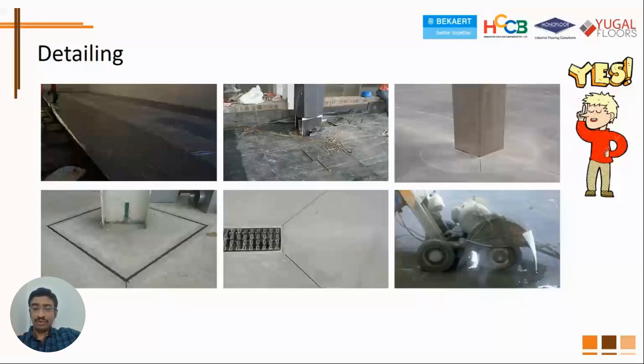And also you could have a detail where you could have a circular detail like that, so you are preventing stress concentrations, but also you are having sockets at corner columns, so that any cracking emanating from there is routed through that socket. Also some sort of diamond detailing, which is quite common, in the fourth image. The fifth image is that of a trench. You could have cracking coming from there, so it's quite possible you could have a groove joint provided that way.